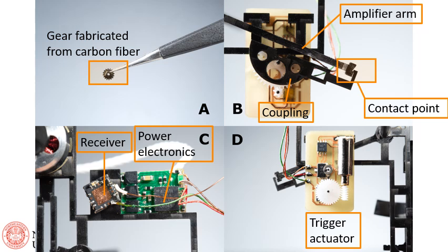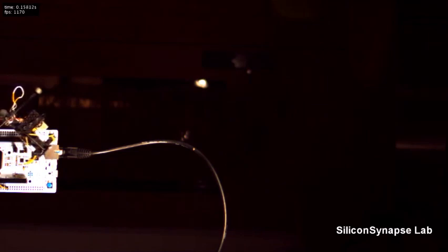Since the projectile is charged with massive elastic energy beyond the output performance of the trigger actuator, a force amplifier with 1:40 mechanical advantage is designed and fabricated at millimeter scale. In our experiments, only the longitudinal motion is considered.